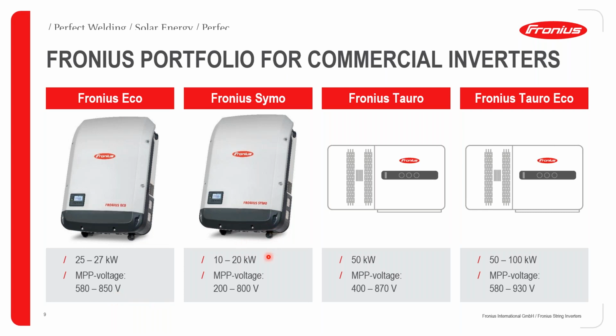Then moving on to the Fronius Simo, it comes in power classes of between 10 to 20 kilowatts. Your MPPT voltage range is between 200 and 800 volts DC. So again, please try and get your strings within this voltage range. You can see that the Simo has a much higher range than the Eco in terms of the MPPT voltage range, and this is because the Simo has a booster circuit integrated in the inverter, whereas the Eco does not have that booster circuit.